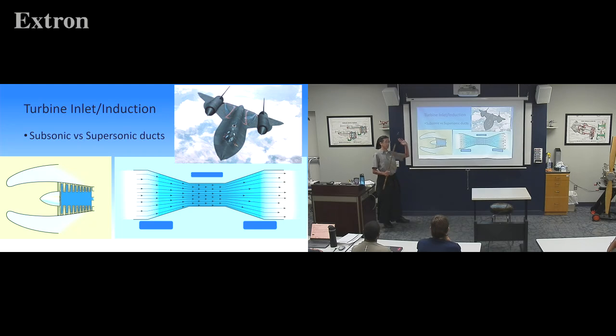It's a little hard to tell because it's not a big difference, but it does diverge a little bit so that in the inlet, this pressure is going to be higher because that's how it is designed, to get all the pressure we can to our compressor. Does it also converge a little bit with the spinner? Yes, a little bit, but this outer has more of an effect overall. But that's a very good observation, yes.